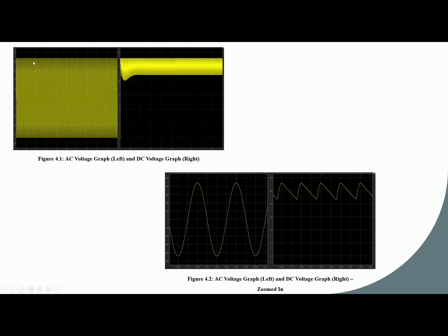We have the AC voltage graph on the left, which is oscillating at 220 volts peak voltage and 50 Hz frequency. Then we have the DC voltage at the right side, which is rectified from the AC voltage and is oscillating between 22 volts and 28 volts at a stable condition in the positive cycle region, but never in the negative cycle region. The filter capacitor in the full wave rectifier circuit has done its function in smoothing the waveform of the converted DC voltage and stabilizing the voltage in the laptop load and battery.